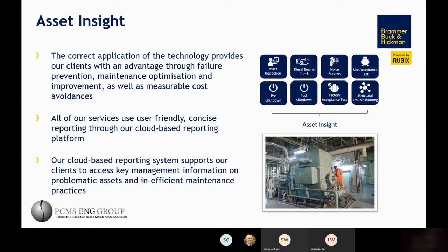Diesel engine checks. Using PeakVue technology from Emerson, we produce a plot for each cylinder, showing the firing frequency and valve operation for each. Using this, it's possible to identify faults such as over and under fueling, cylinder or piston ring wear, and injector problems. As a result, small repairs or adjustments to the firing or fueling can increase the efficiency and life of your engines.